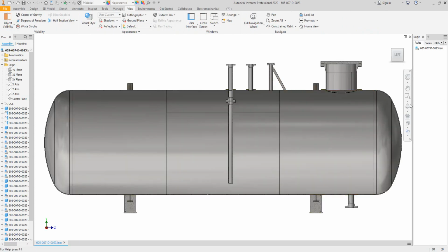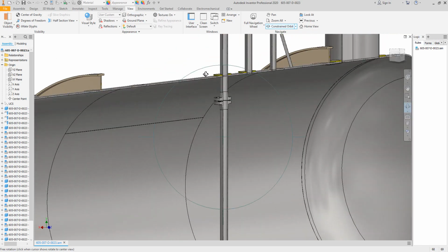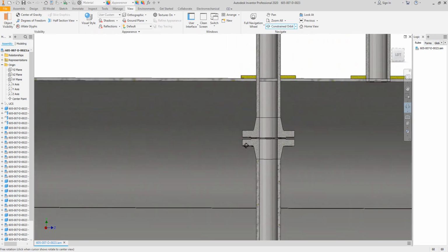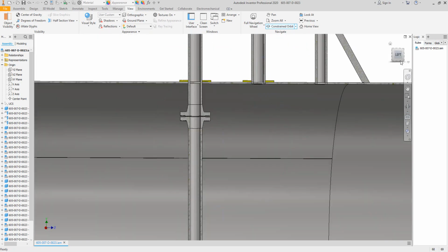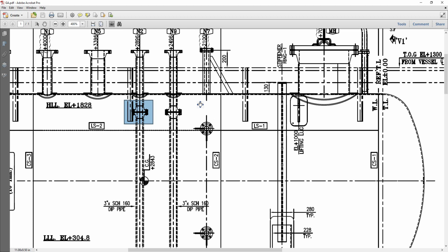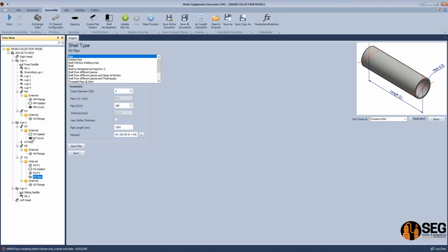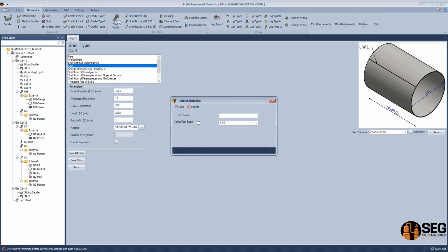Okay, so by that way you can modify or create a nozzle with internal projection and add connected elements to the internal connection of this nozzle. By the same way, we could make nozzle N9. Okay, so let's go to the next nozzle, which is N5. From here, let's select CAN 2, and from elements, let's add N5.